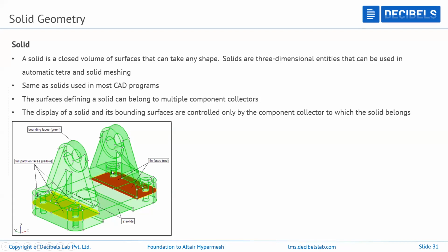Basically, solid means the geometry will not have any discontinuities or any missing surfaces. Then that geometry comes under solid CAD or solid geometry. The geometry is completely enclosed by a volume. In most cases, when we are using design software, we work with solid CADs only. But when it comes to CAE software, we delete that solid and carry the meshing on the surface. After deleting the solid, on top of the remaining surfaces, we are going to create the solid elements.